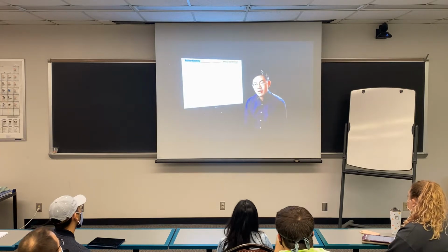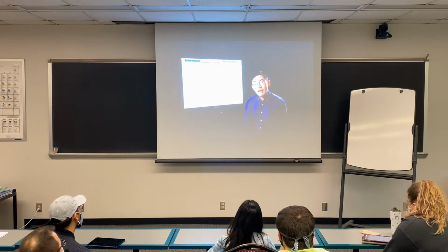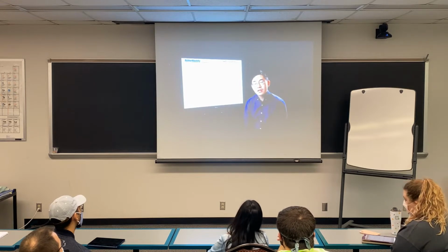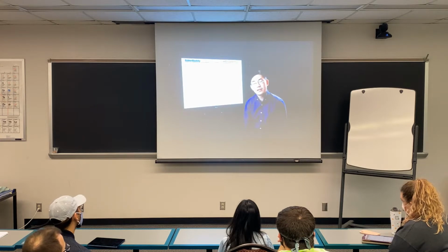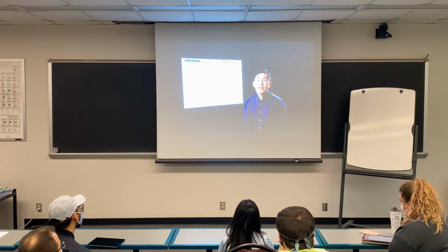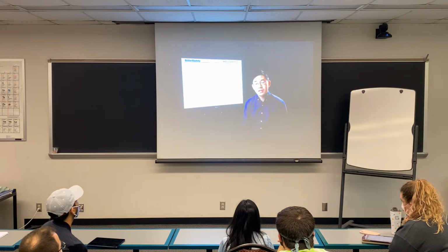Okay? This crystallization happens to act as a physical crosslink. It's not a covalent crosslink, but it's something similar. It's called a physical crosslink, where the crystallized points basically act as crosslink points. And as you can see, if we happen to have physical crosslink points between those covalent crosslink points, then you would have artificially increased crosslink density.